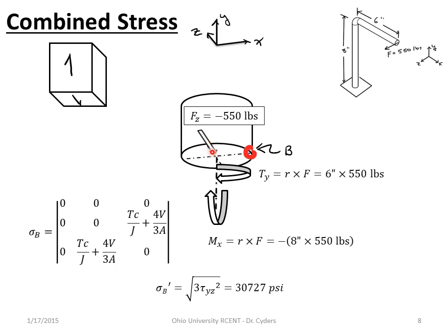So, of course, we picked an element here at A and drew it, constructed the tensor, found an effective stress. We do that for all the critical points, all those points where we think, I need to assess the stress at this point because I'm not sure which one of these is going to be greater, but I can do a little bit of a thought experiment to say, well, the stresses here are going to be greater than the stresses here, and the stresses here are going to be greater than the stresses here. So let's pick some points on this cross-section, and based on what types of stresses those are, I can pick my critical points, construct my tensors, and then, as we'll see when we go over plastic failure criteria, I can sum that up in a criterion that I can then compare to a fixed yield point.